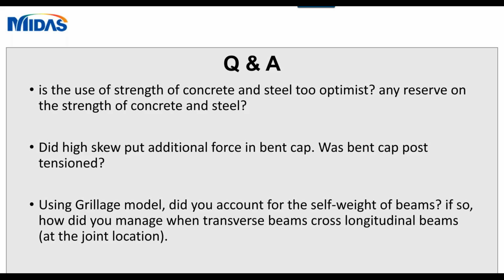So all the weight and properties of the beams account for the slab in the longitudinal direction, but the connection between these elements, the slab in the other direction, is also not adding weight but influences the stiffness. So I have to define area and inertias of those elements. I think that answered the question.